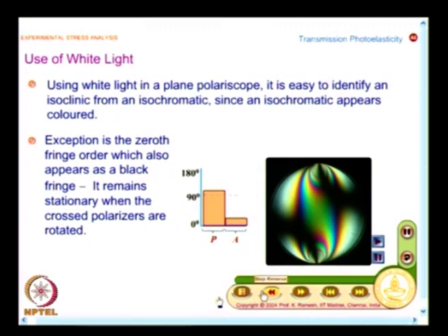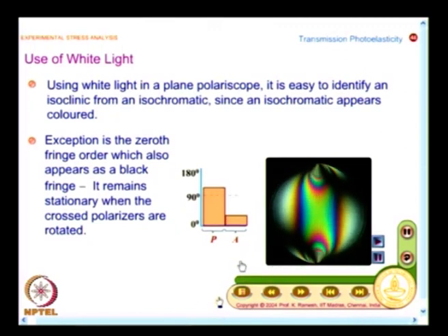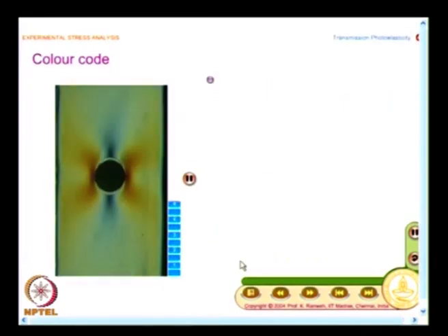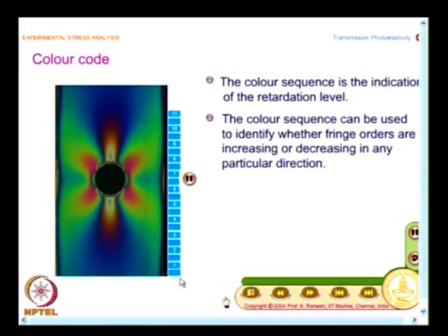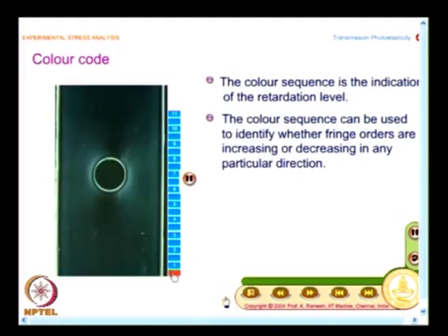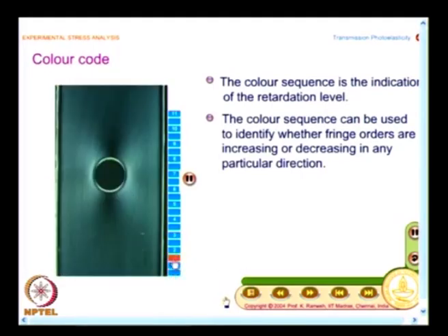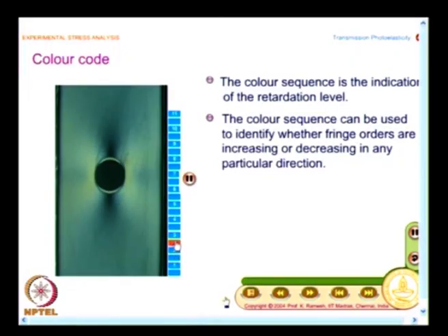You all know stress concentration. We will look at a plate with a hole, how do the fringes develop. So beautiful. We will see one after another. I have the load gradually applied. When I gradually apply the load, colors start appearing, and also observe where the colors start appearing.